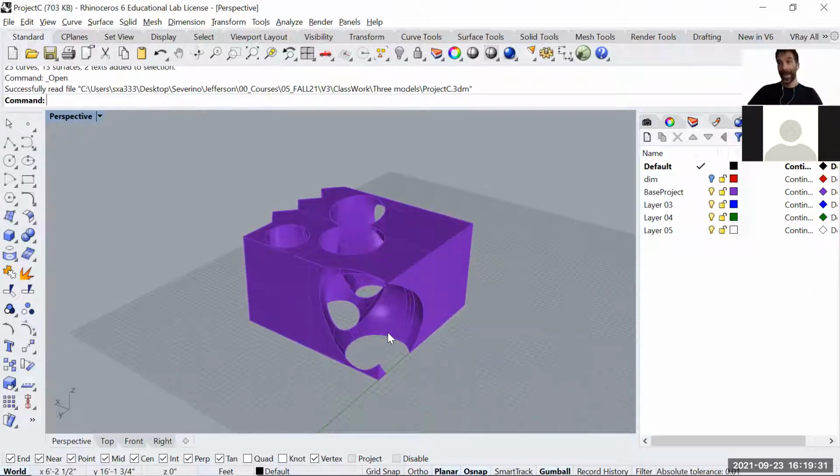Just keep in mind, you can't laser cut a real scale house, for example, because that would be building a house. So we need to reduce scale, maybe 10 times smaller, whatever it is. And to scale, you use the scale tools from Rhino or from AutoCAD. Scale down by a 0.1 factor, 0.01 factor, whatever is ideal for you.